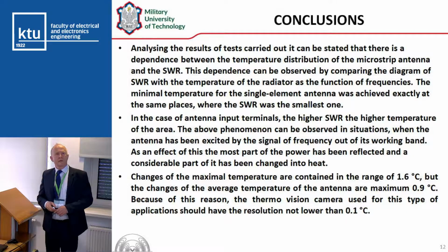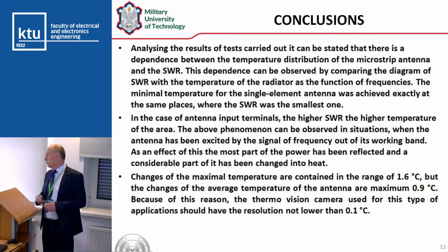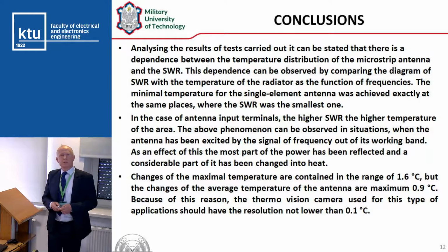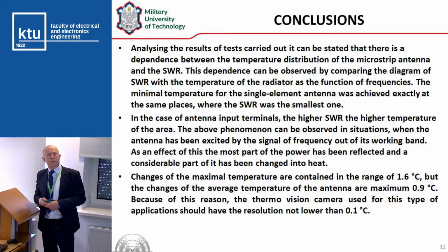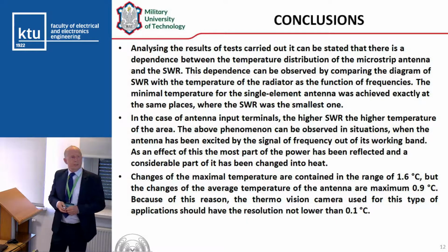The above phenomena can be observed in situations when the antenna has been excited by a signal of frequency out of its working band. For these frequencies, the standing wave ratio has the highest value. As an effect of this, the most part of the power has been reflected and a considerable part of it has been changed into heat.